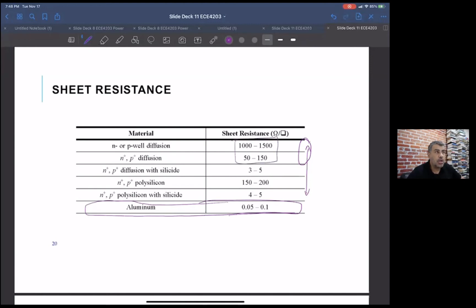As you run out of interconnect layers, and you get into some tight areas, you'll be surprised. People start getting desperate and using these layers for connections, and it invariably bites you in the rear. So maybe for very short distances, if you have poly with silicide, but I really wouldn't use anything else.